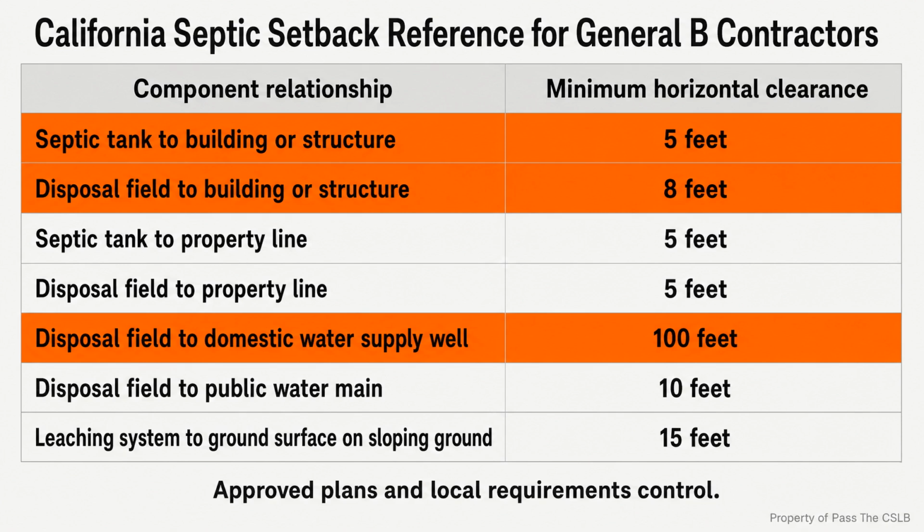The reason is not mysterious. A concealed, unfilled void can collapse later, and remaining waste creates a health hazard. Proper abandonment removes the contents, eliminates the unsupported top, and fills the space so it no longer behaves like a buried cavity.